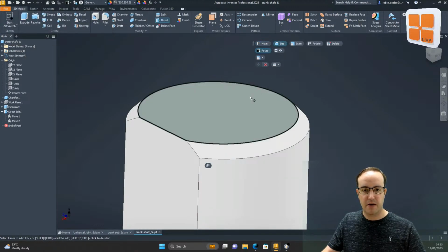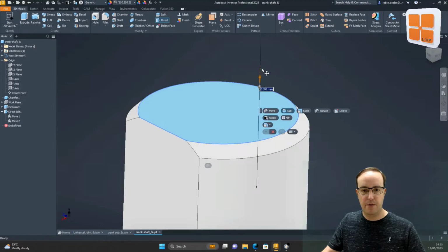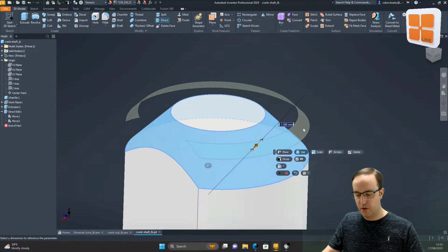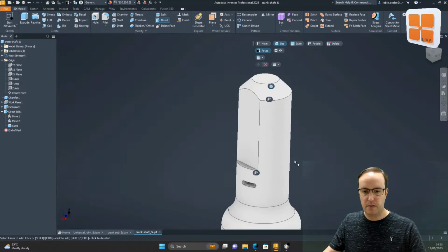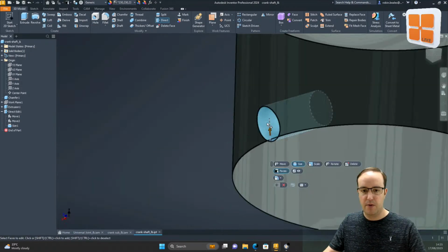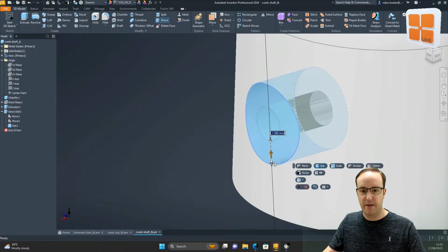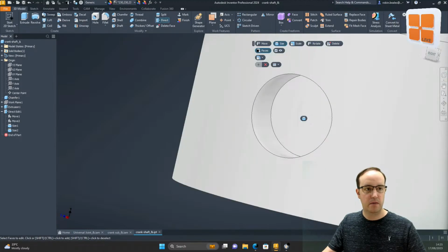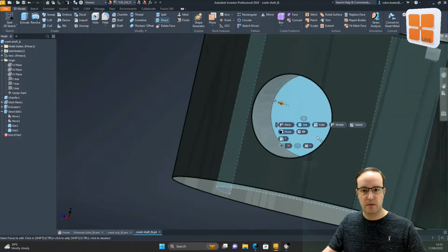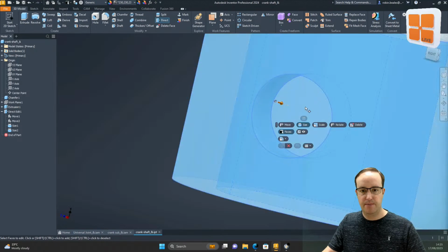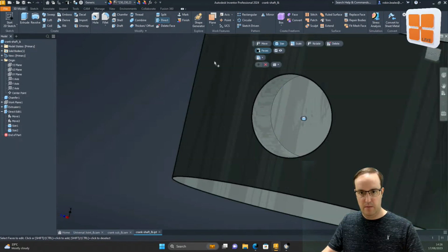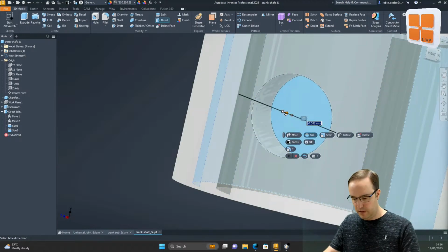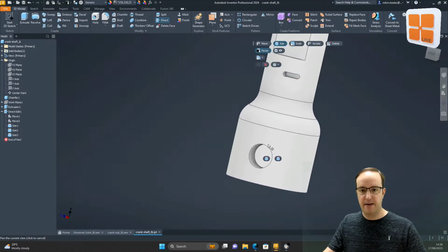And we're going to grab our size tool, and we're going to resize the chamfer that we've got on the top here. I'm going to come to this hole at the bottom, grab the hole and make it bigger. I'm going to grab the depth of the hole, make it shallower. Screen is a little bit jerky, which I'm going to apologize for, but I'm going to go with it. Make that a little bit shallower there.